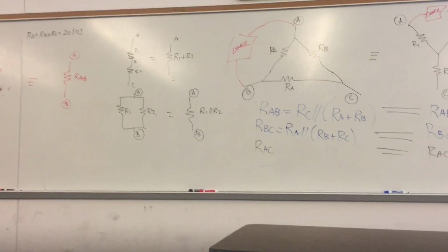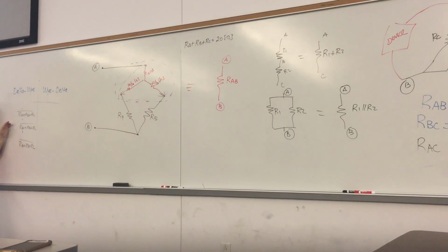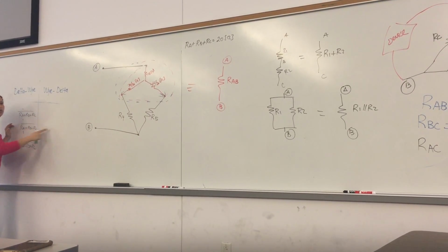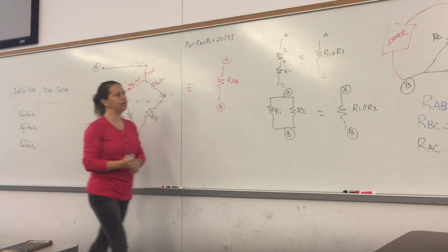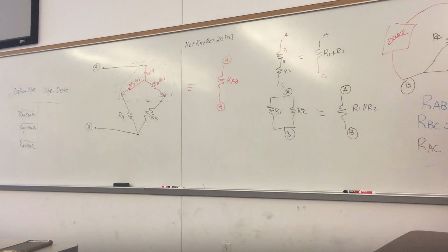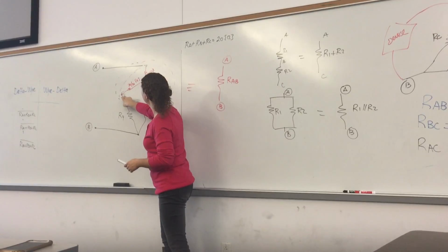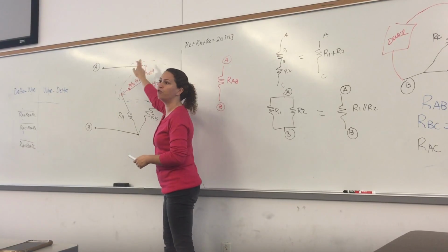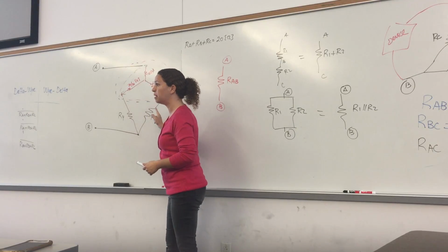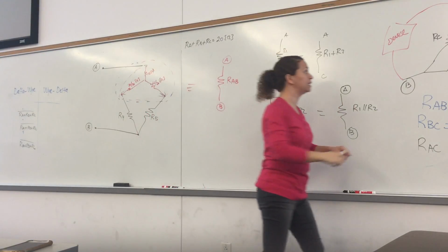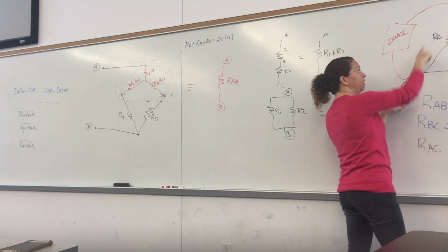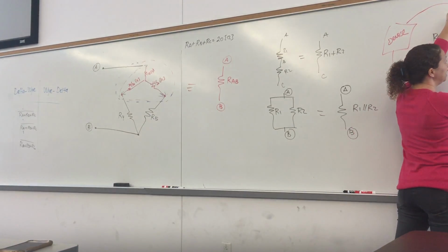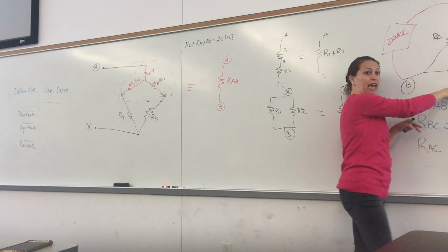If you look at those equations in the PowerPoint, it says A, B, C, R1, R2, R3. Are those random? Can anything be RA? Not really. If you want to go with this labeling system, what I do is label A, B, and C, and it doesn't matter how you put the A, B, C on those three terminals. Could be A, C, B, or A, B, C. But once you put the A, B, C's, put RC between A and B, the missing letter. Between A and C, B. Between C and B, put A.